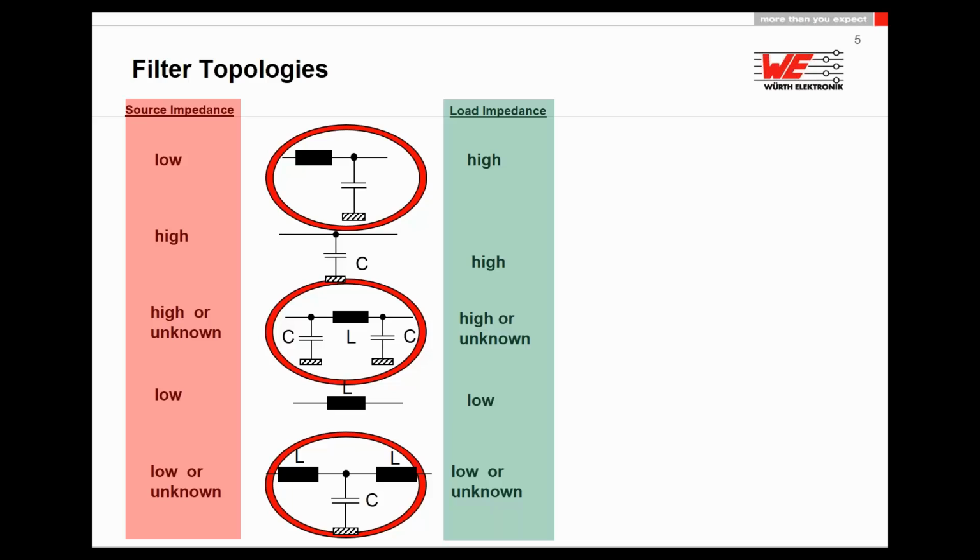So the T filter or P filter or even the LC filter, if it is recognized that it is a differential noise, because first of all you have to know it is a differential noise. For a common mode noise it will not affect too much, and you know exactly where the noise is coming from, which is also not so easy to find, I know, then you can try to use this LC, P or T combination.